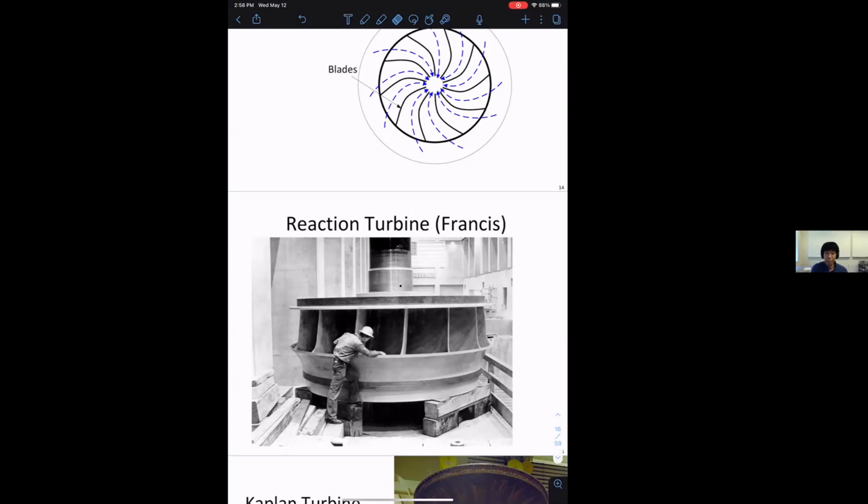It depends on the volume, the flow rate, and the velocity of the water. But your velocity is built up by going through a very high head, right? Going through a large drop. And your flow rate depends on the volume and on the flow rate into the reservoir and a bunch of things. It's really dependent on exactly the setup of the reservoir. But the idea is if you don't have enough water, then you need the water to have high speed, and that's when you have to use an impulse turbine. If you have a lot of water, you can use a reaction turbine. I see. Yeah.